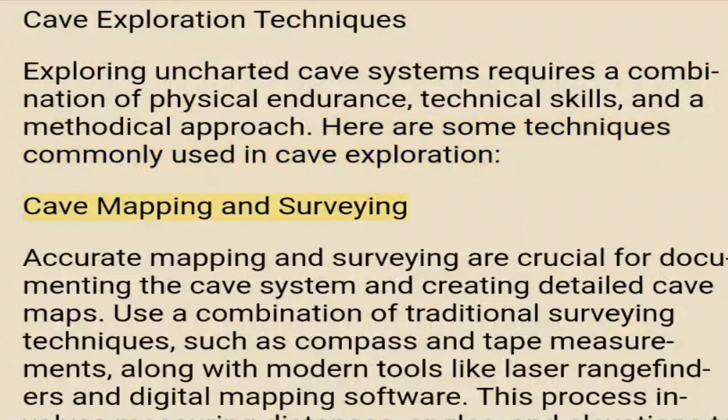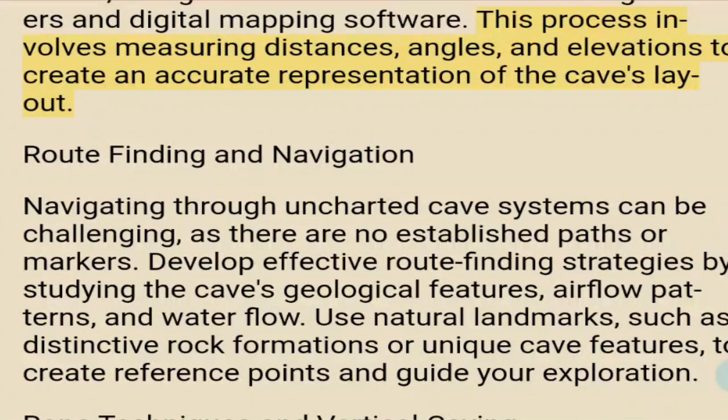Cave mapping and surveying. Accurate mapping and surveying are crucial for documenting the cave system and creating detailed cave maps. Use a combination of traditional surveying techniques, such as compass and tape measurements, along with modern tools like laser rangefinders and digital mapping software. This process involves measuring distances, angles, and elevations to create an accurate representation of the cave's layout.